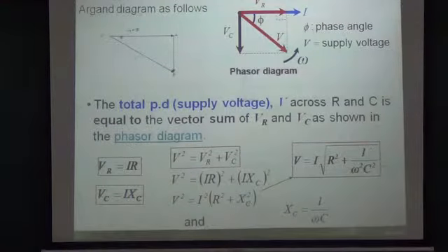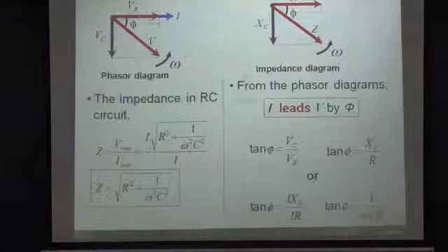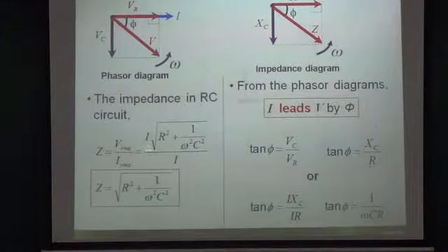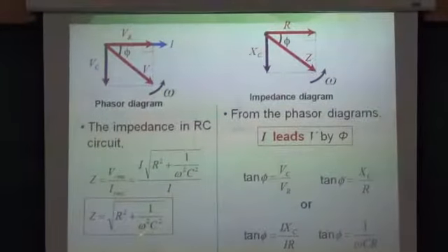I into this square root of. Now this has dimensions of ohms, and hence we call it impedance, which has two parts. So Z is the impedance, which is VRMS by IRMS. So you can always write the impedance of the circuit, and you can see that it is frequency dependent.